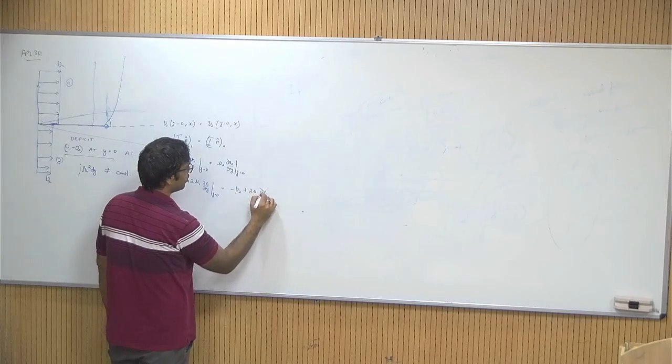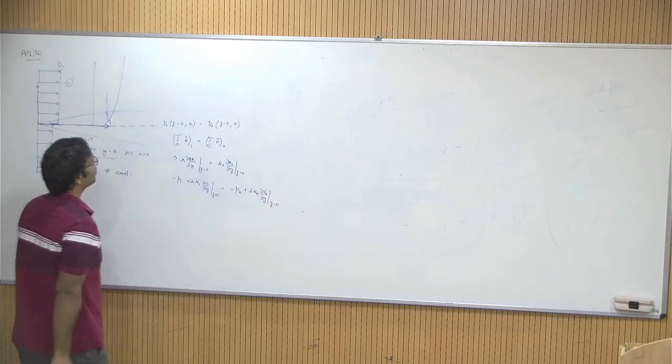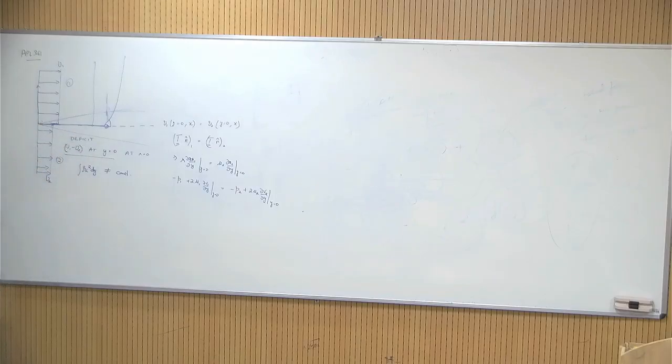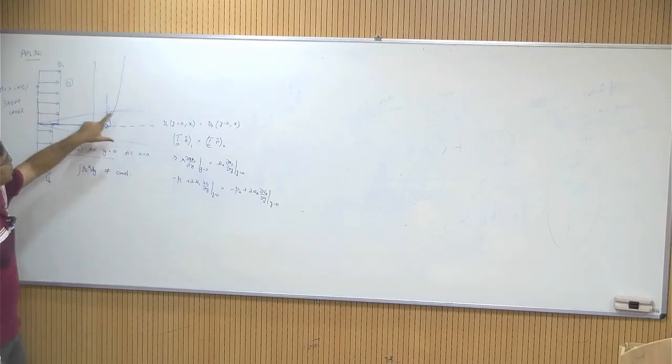This you will get from the stress boundary conditions. So you have to use these, and then you can convert this system into a Blasius type of a system. So this is called a mixing layer, or in some places you may also see it called a shear layer. The name is in a way self explanatory. There is a shear that is diffusing as you move downstream.